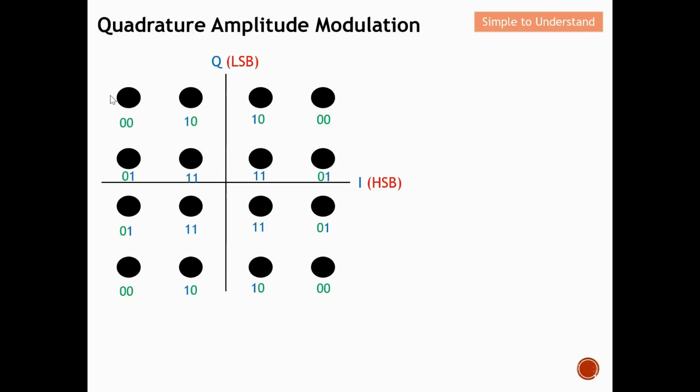So next, I'm going to do the third bit. How can I actually do the third bit? Again, this will be the lower sideband and this will be the higher sideband. How should I do this? Let's say this is a message. Since this is 16 QAM, I know that I can separate it into 4 bits. 2 to the power of 4 is equal to 16 levels. So I know that I'll be controlling 4 bits here. From here you can imagine that this 2 bits here will be represented by the 4 QAM which I illustrated earlier on.